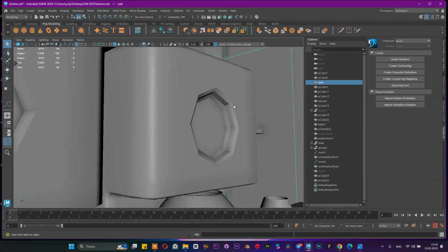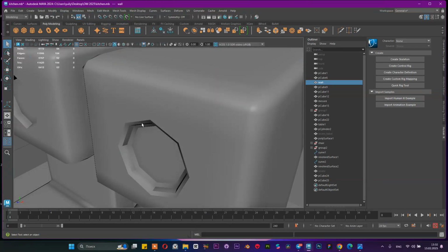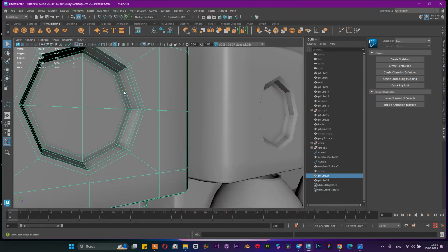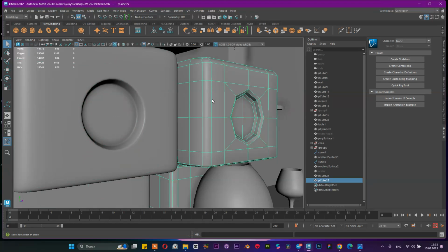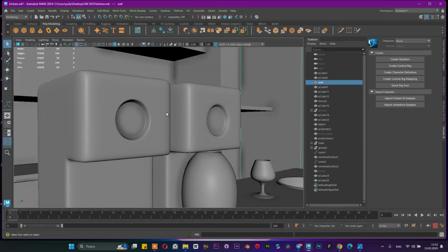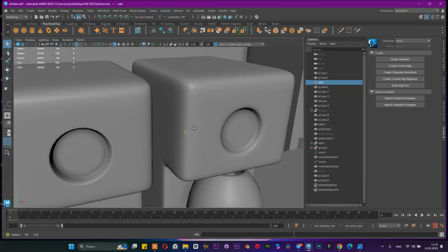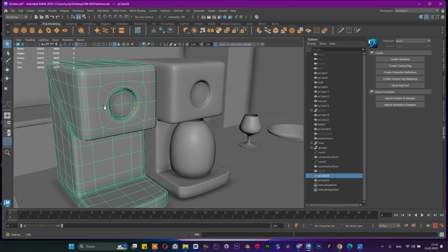With the chamfer, we have some nice and accurate smooth, but without chamfers, we didn't see this smooth. But when we create a smooth mesh preview, it looks more sharpened, like this. And this technique is used in hard surface modeling.